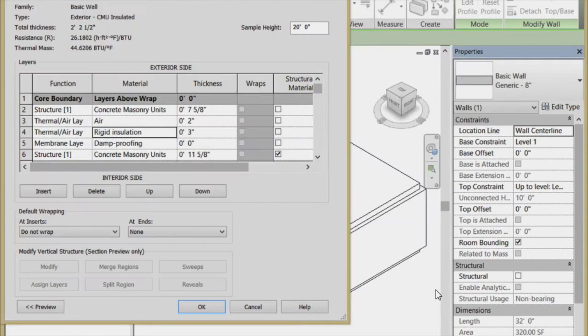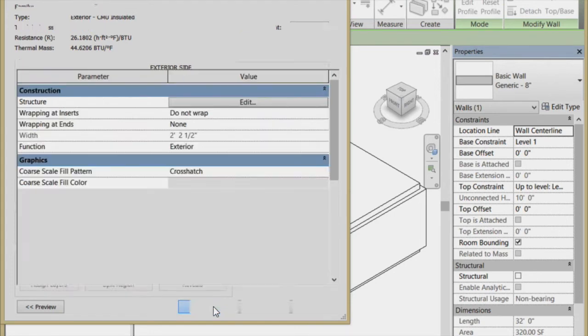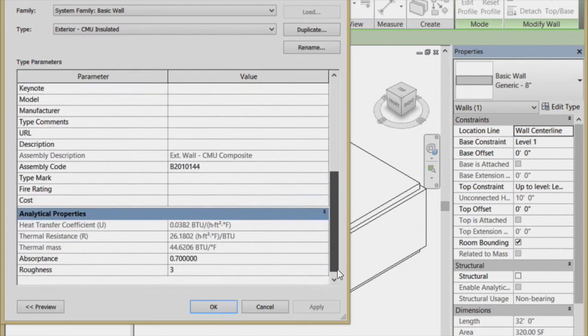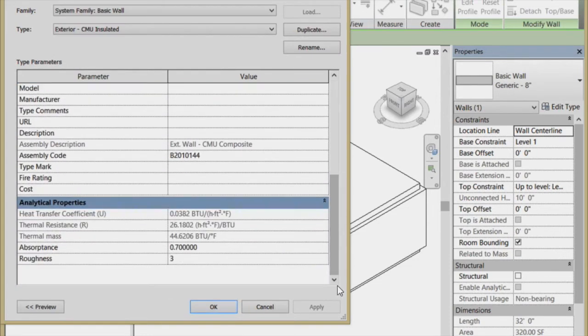And there's the density. See, you munge all this together. So basically, I've got a rigid insulation layer right now. It's 3 inches. Right now, that rigid insulation layer, along with everything else, is basically delivering a wall with essentially an R26 value to it. So if I wanted to go ahead and raise it, let's see how big the impact is.